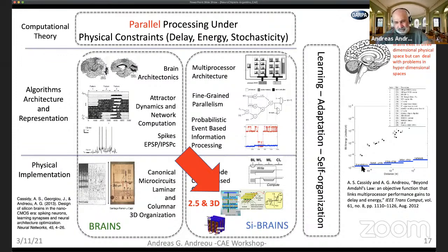Bits can travel within a small circuit, within a transistor itself. They can travel within a functional unit. They can travel within a chip. And this is roughly the energy that it costs for a bit to go from a single transistor, which is somewhere about here, to the end of the chip, which is something about 10 to the minus 14, and to the board level, to another chip, which is 10 to the minus 12 joules.